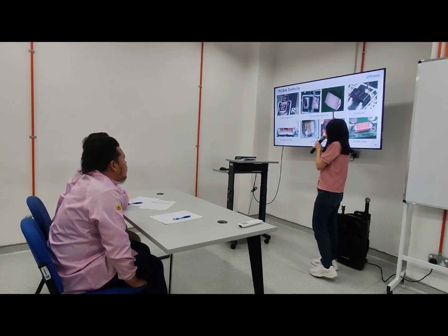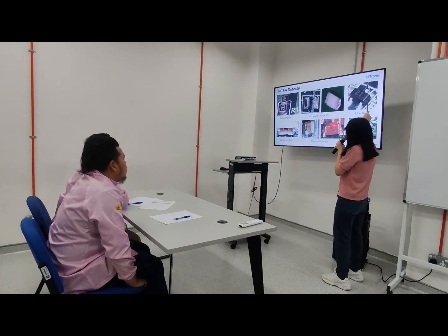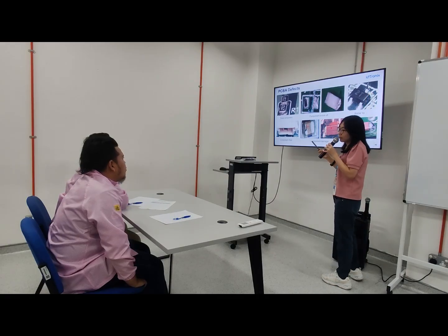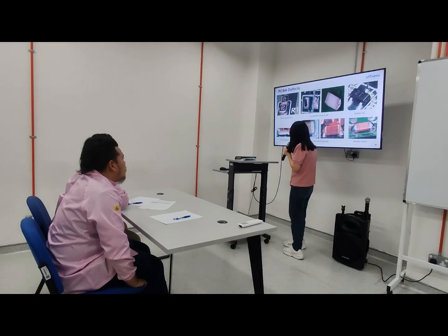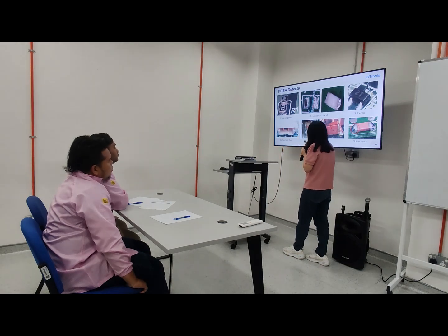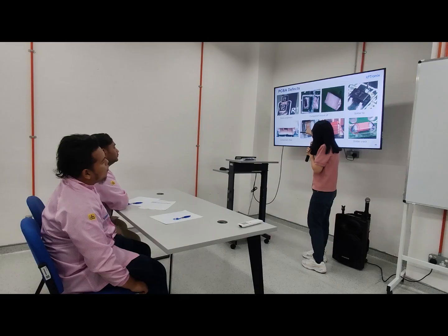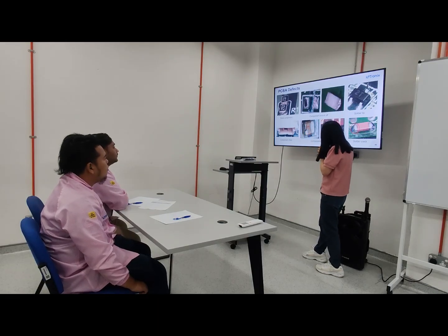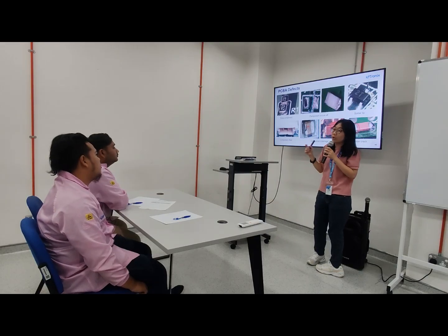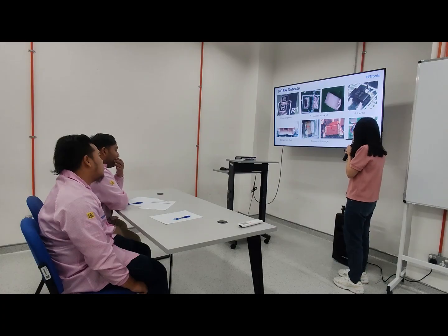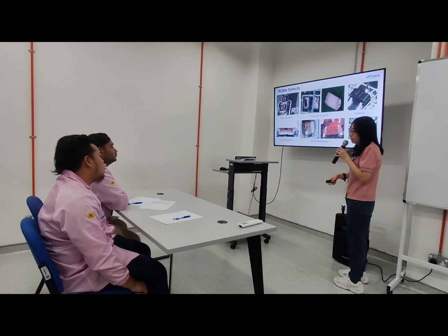Below. This one? Solder, yes, sharp. Here, this one the solder is sharp. What is this? Yes. Lifted, then it has a big gap. This is component damage. The component body is already damaged. And here, you see? The component has cracked. Next we have the solder crack. See this line? The solder has cracked.